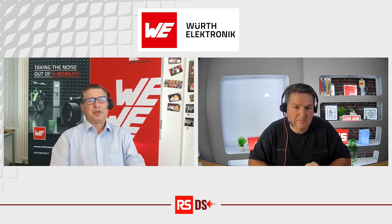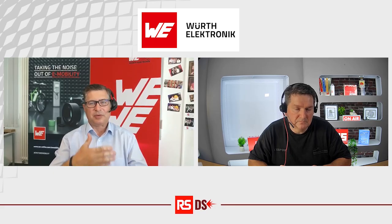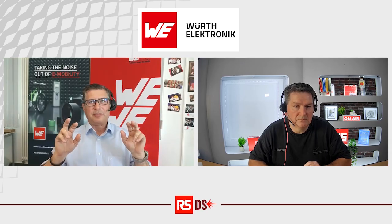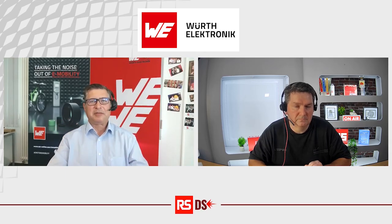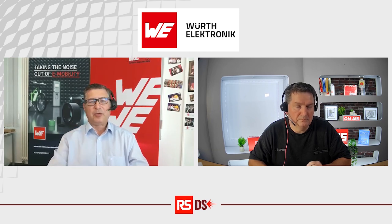For the DC blocking, it's actually quite simple. Normally, in a typical application like an audio input, you have a capacitor which should block the DC from the AC. But for more safety, it is this typical 1 nanofarad capacitor which you put on each pin of your input IOs, where you try to face ESD discharging.